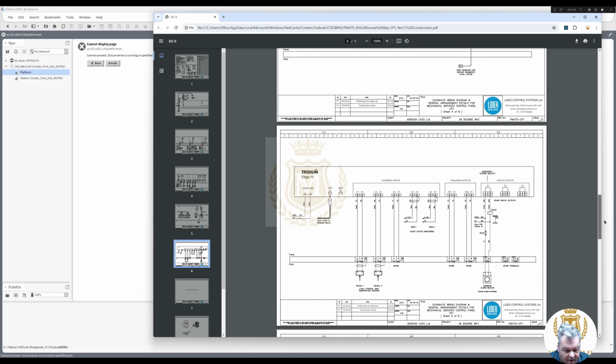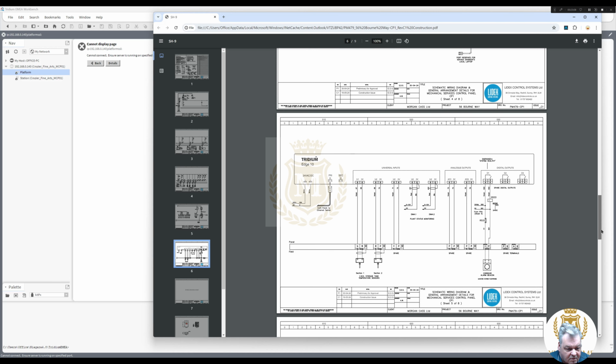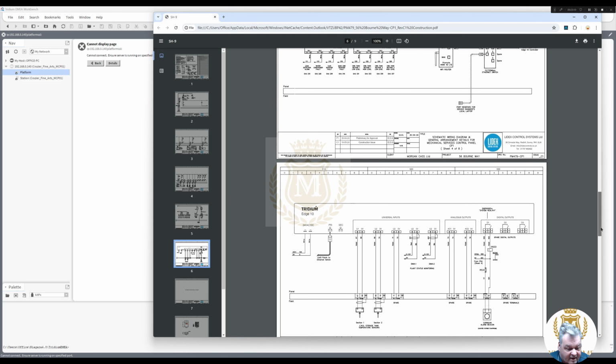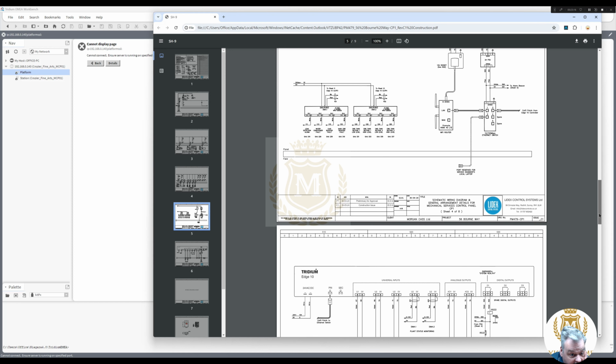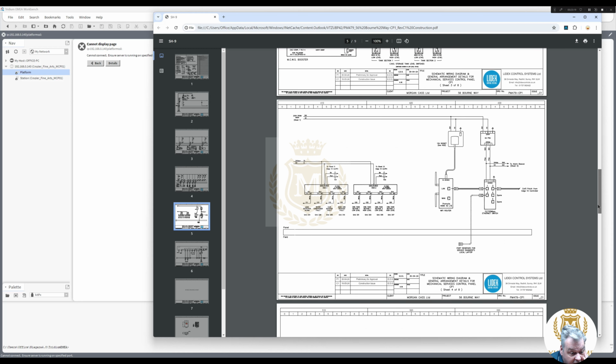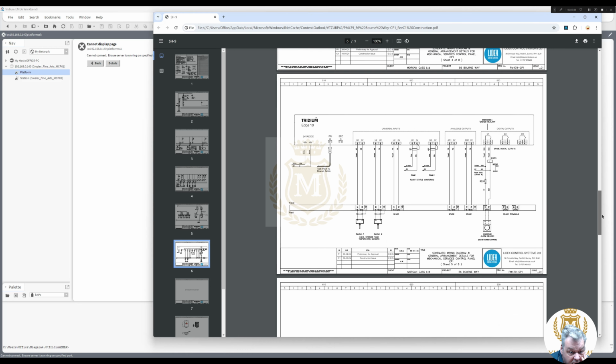And the alarm will be if any of these storage, cold water storage, go above 21 degrees, I would say. I haven't got any details, but that's what I'm going to set it to, but I'll make it adjustable. I'll put a little adjustable thing in there so they can change it if need be on the basic graphic. And then leak detection, water conditioning, gas booster, main CHW booster, they're faults, and all them are faults. Low level, high level, low level, high level. So this is just an alarm monitoring panel because everything is to do with alarms only.